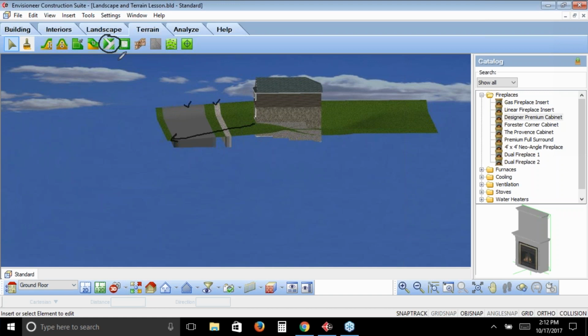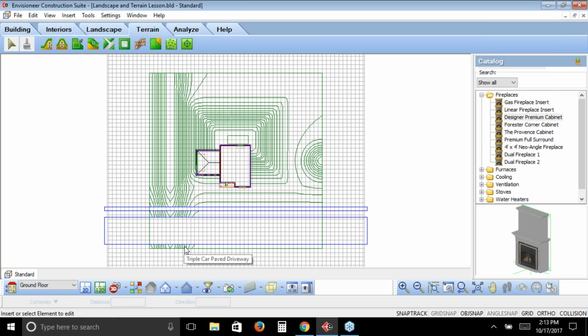But when it puts in a path, you can see that when I'm getting down here and I'm going down -4 feet in my terrain, that this roadway is actually meeting that -4 feet as well. It's going down and dropping down that entire height as well. So you can see the thickness going in there as well. I'm just going to erase all those drawings I just put in and go back into a 2D view.